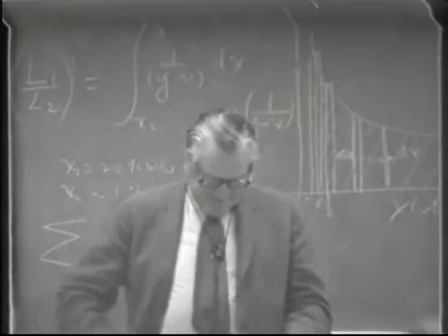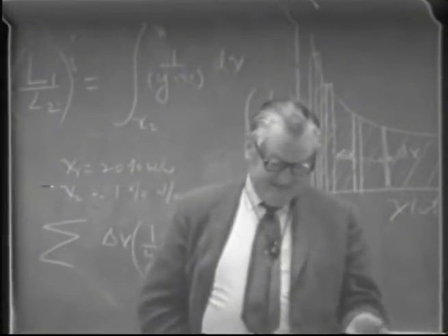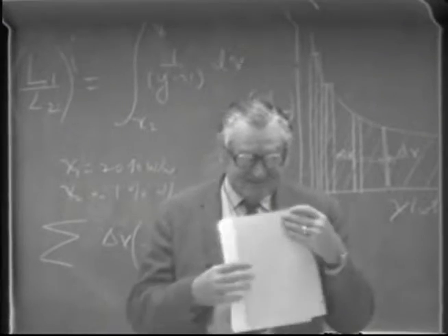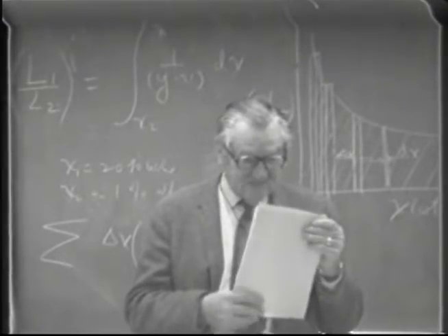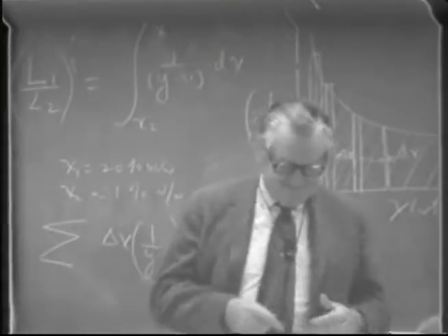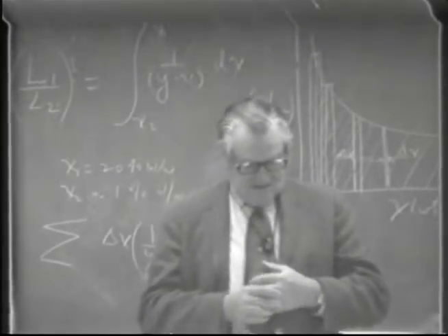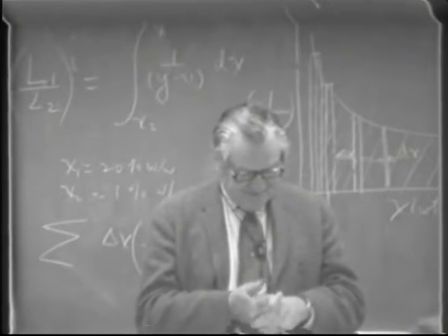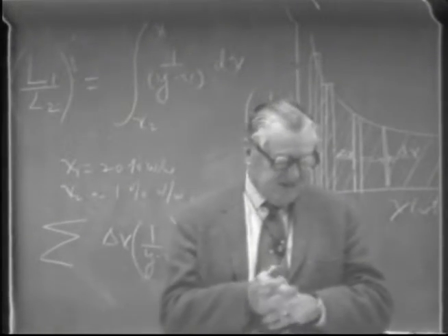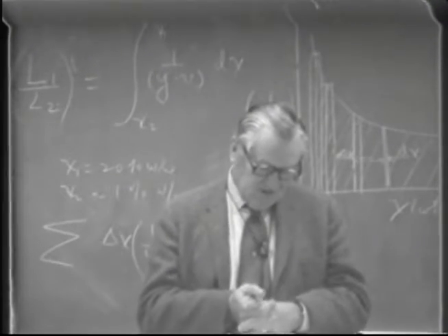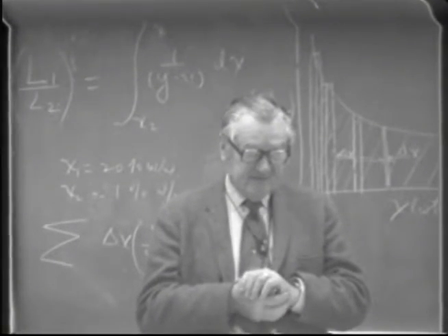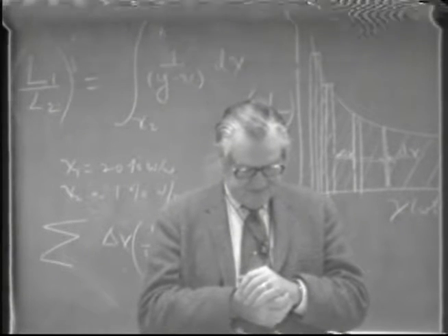Well, one of the most common errors is drawing it off at the wrong level, at a tray where there isn't any. So that's one of the main problems in operation, is to operate the column in such a way that the higher alcohols are in the region where you're going to draw it off. So I mentioned, as we have already before, that the tray that's about closest to indicating a strength of 130 proof, which is around about 185 degrees Fahrenheit, would be the area of maximum fusel oil concentration.